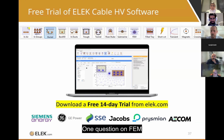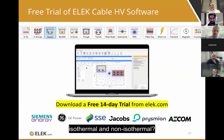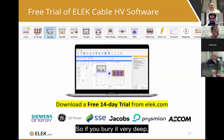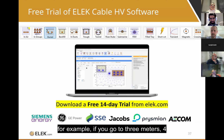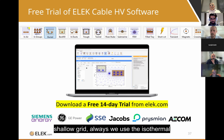One question on FEM was what difference do we expect to see between isothermal and non-isothermal? What I would say is it depends on the depth where you bury it. If you bury it very deep, for example 3 meters or 4 meters depth, you will practically see no difference, because non-isothermal conditions become isothermal when you go to a deeper cable. But if you are burying very shallow, for example 0.1 or 0.2 meters below the ground surface, you will see a significant difference. We have seen more than 10 to 15% difference in cable ratings between isothermal and non-isothermal conditions. So if it's shallow buried, we always use the non-isothermal process.